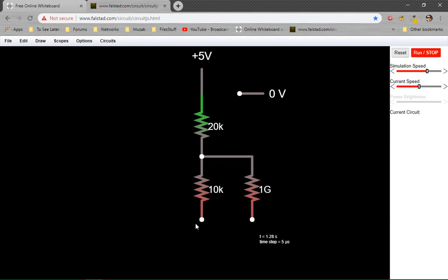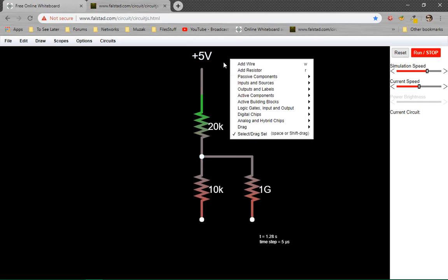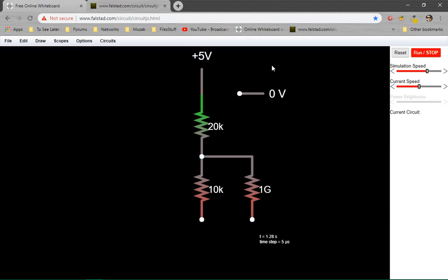All circuits will have a point to which everything connects, and that isn't at 5 volts, because lots of circuits have various voltage levels. The only thing in common between all systems in a circuit is the zero, what we call zero, the reference zero. And we call that ground, or, as we may guess, the common connection, because these two are supposed to be common to each other, or in other words, be connected to each other.